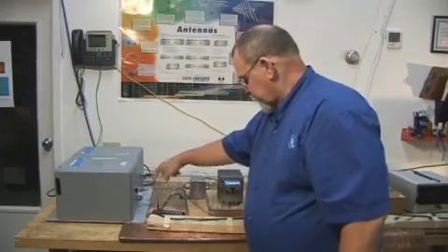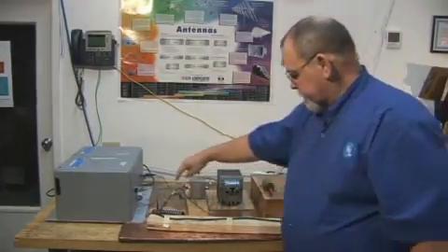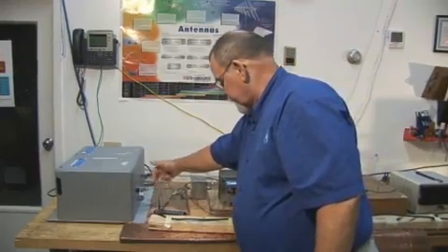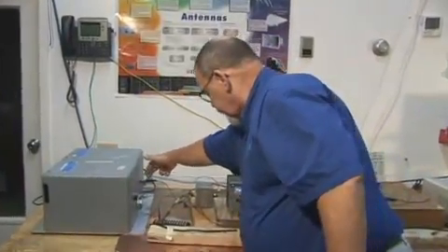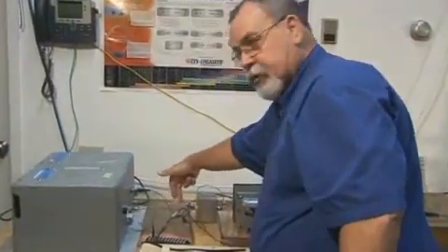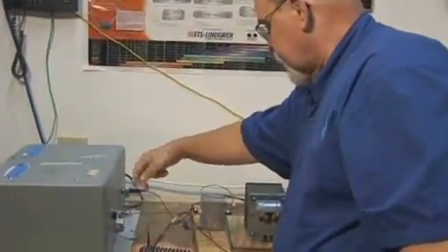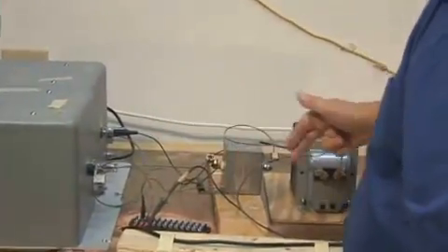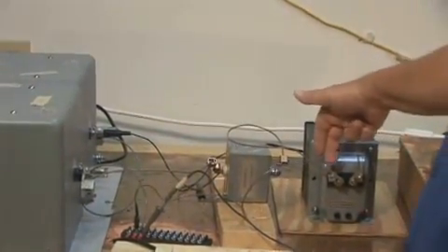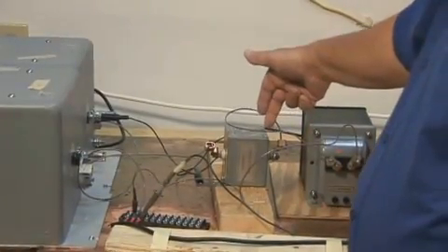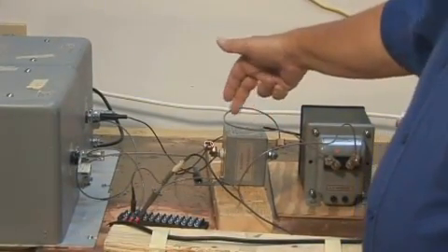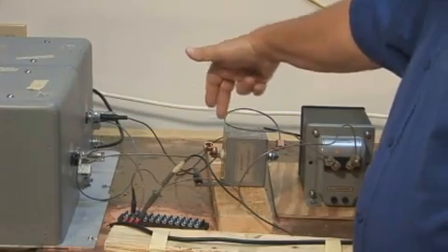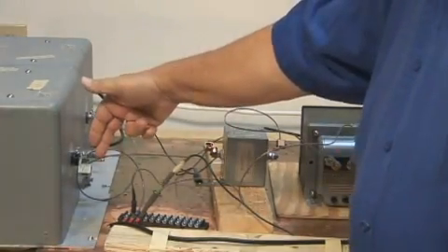I have the oscilloscope wired to the item to monitor the applied voltage. I have the neutral leg going to my LISN, and the LISN also connected to the return of the feed-through capacitor. I have the positive side, or the phase lead, wired to my coupling transformer, from the coupling transformer to the capacitor. And remember, the capacitor is parallel, but since this is a feed-through capacitor, we go straight through for the one side. And this comes back to the phase side of my LISN.